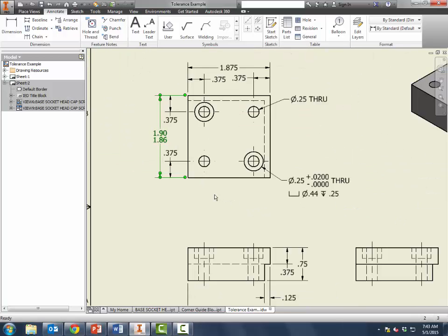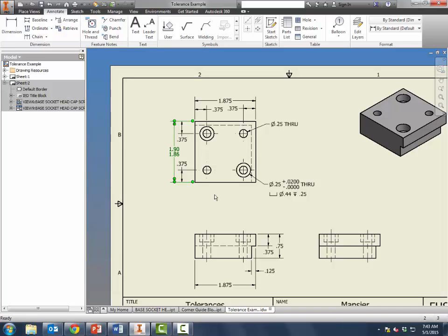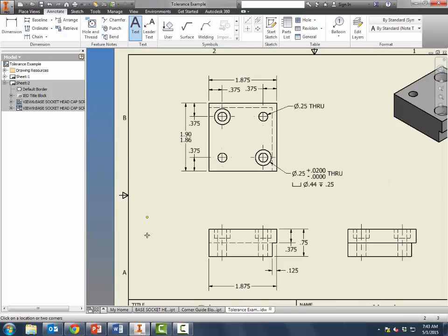Okay, so the goal for this activity is to take two of the parts that you actually used in your reverse engineering project that physically connect together, start changing the tolerances of the parts that actually connect, or the pieces that really matter. Because if I look at this, does the overall length matter when it comes to whether or not the screw is going to fit inside this piece? No. The holes where the screw goes in are going to matter, and that's where we're going to add the tolerances.